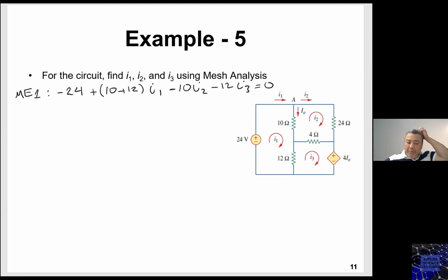See, now things became clearer. You became more confident. You know now what you're looking for. You know now that two mesh currents with the same orientation, clockwise or counterclockwise, mean opposite directions in the shared components. Now things became easier, and you wrote the mesh equation right away by inspection, and this is great. Thank you, sir. You're welcome.